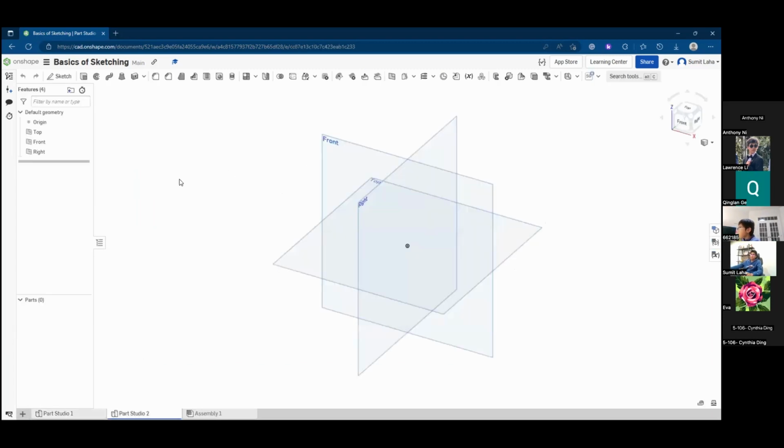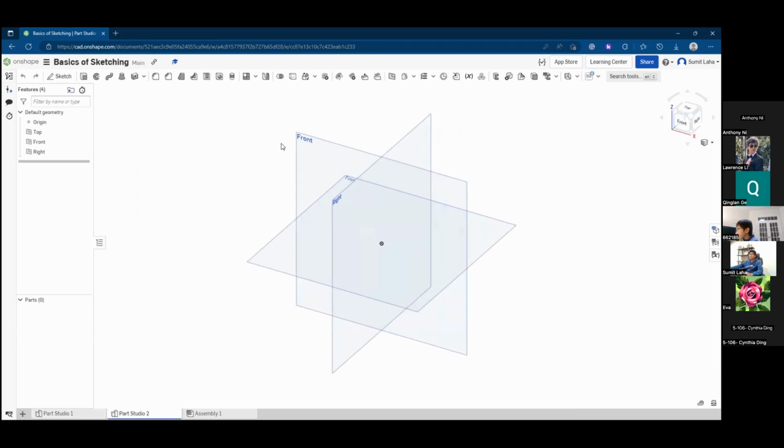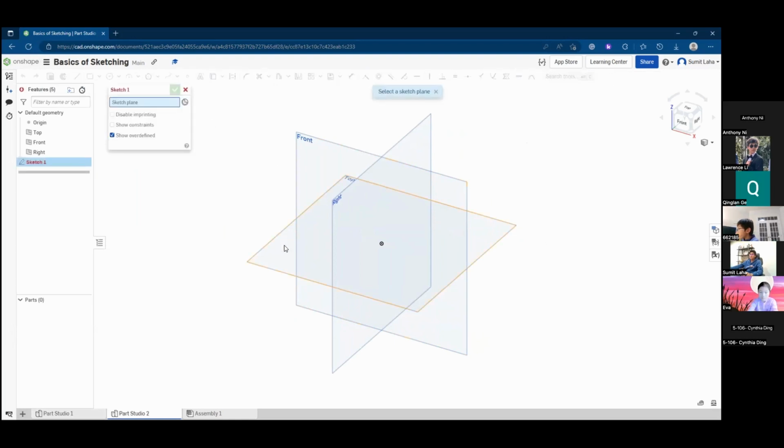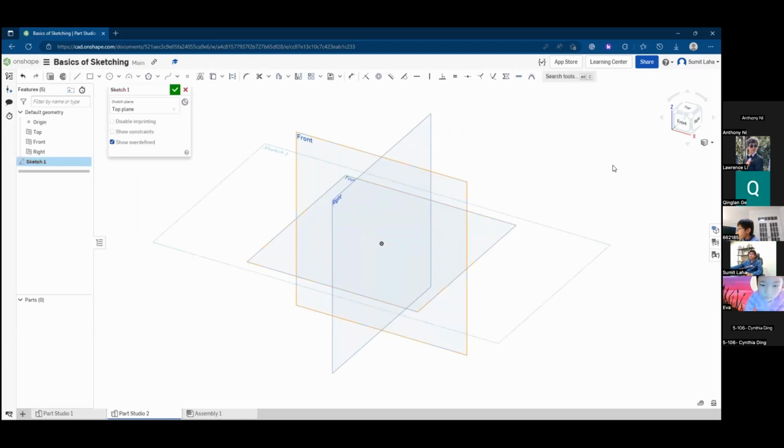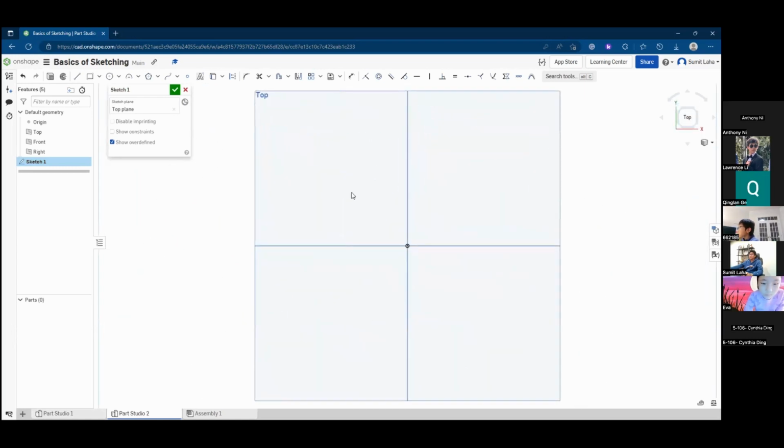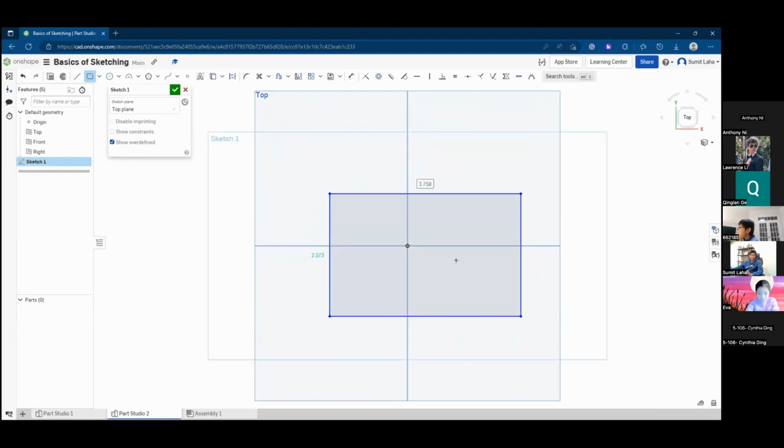All right. So you remember how we created a sketch, right? To create the sketch, we click on the sketch tool, we click on the plane, and then we come onto the plane, right? So last time we drew a rectangle like that. It was a random rectangle. But say we want to change the sides to be a specific length, right?